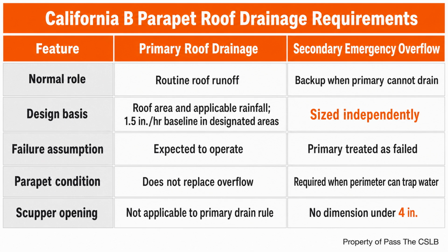During framing and rough coordination, I verify the secondary opening is actually framed, that its elevation matches the plans, that its path is independent, and that the minimum opening dimension is maintained.